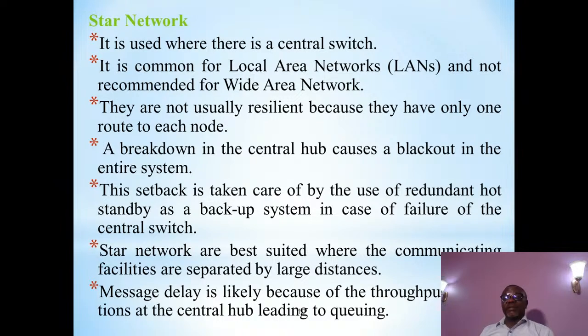So in telecommunication systems, when you have such a layout where a center is controlling all the other connections, it is always good to have a standby or a backup or a parallel working switch, so that if one fails, the other one takes over automatically. This taking over automatically is what is known as redundant hot standby in telecommunication systems.